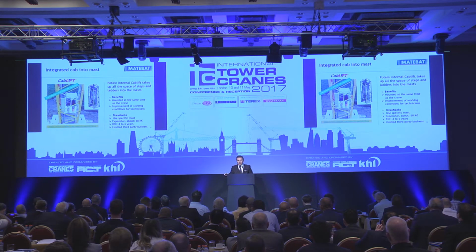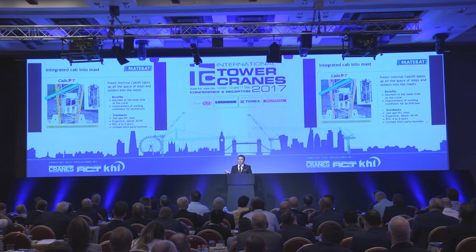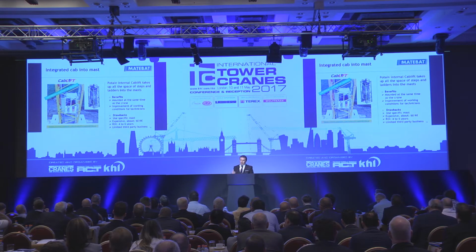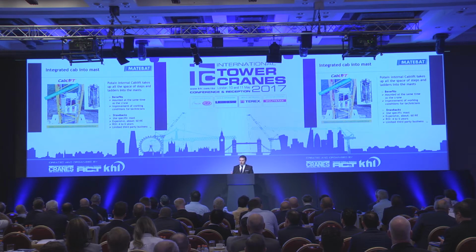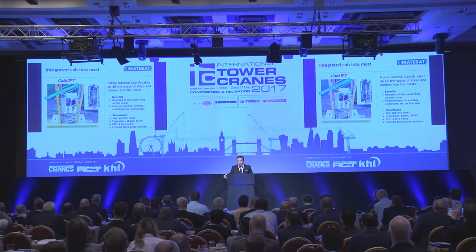The main benefit, obviously, is that it will be erected and mounted at the same time as the crane, because don't forget, one of the drawbacks of the previous solution is that it's another operation. You can't do it at the same time as you are erecting the crane. You have to do it afterwards, so it's more hours, more time, etc. Also, when you talk to technicians, they are more comfortable with the safety of this solution, because you feel more comfortable being inside the mast than outside the mast.